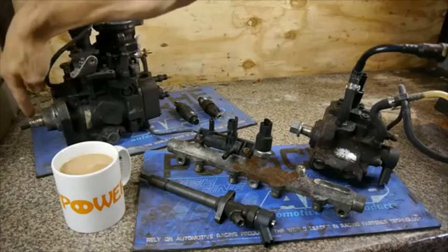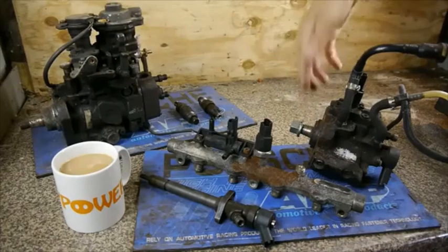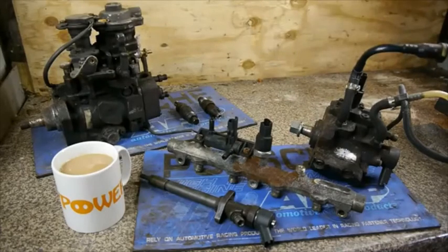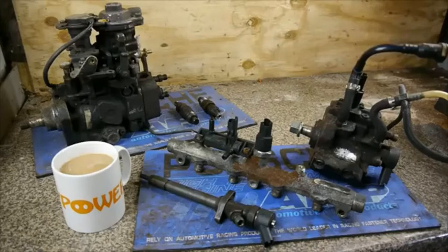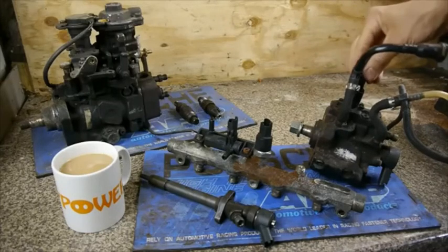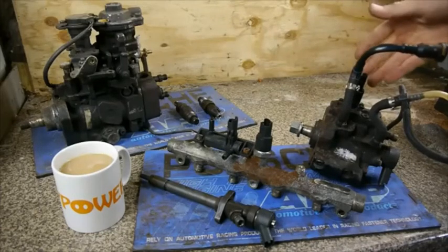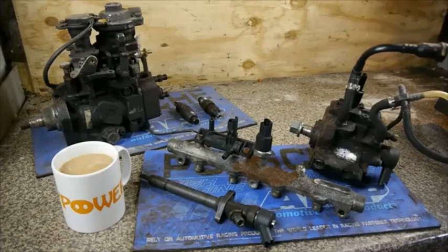They're both driven by a main shaft that goes in, which is usually turned by the cam belt. Later systems have been turned by the camshaft. The initial difference is this runs to a couple of 100 bar pressure, and these latest systems run into the thousands of bars of pressure. A fuel pump like this could easily produce 1700 or 1800 bar of fuel pressure at the fuel rail. So there's the first rather large difference.